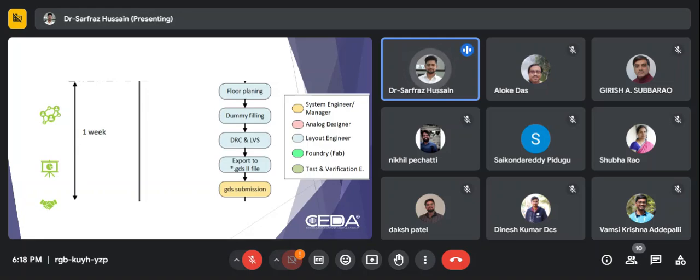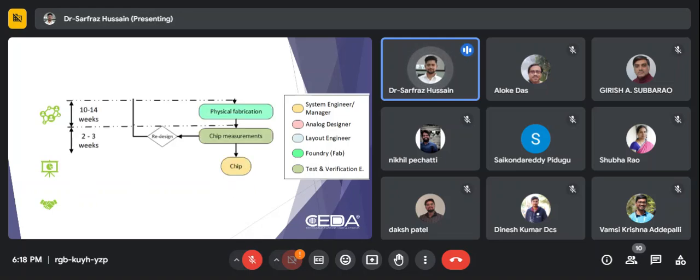with the name .gds2. The file that is saved is a GDS2 file, and GDS stands for graphic data stream. It is a combination of the data stream, like all the data that is required to generate a layout. All of that is stored in a file. After that file is generated, we send it to the fabrication lab.